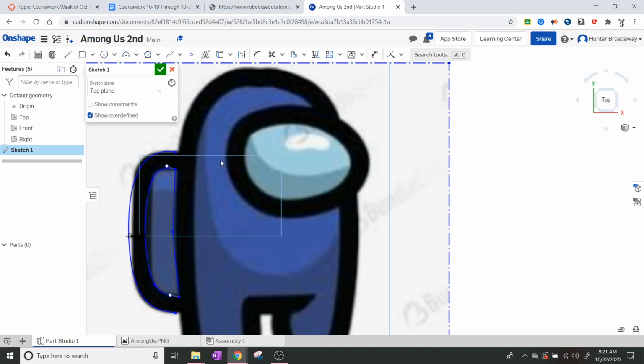Now, okay, so I think I know what your problem is. I think you just clicked and dragged, which means it's going to try to drag the entire surface. So you don't want to do that. You want to click on just the spline part, like this, and make sure that only the spline part is selected, and then you want to select offset because you're only offsetting that part. See how that's the only side that's connected? I'm going to click and I'm going to drag it this way, and it makes the sketch. Okay? Yeah.